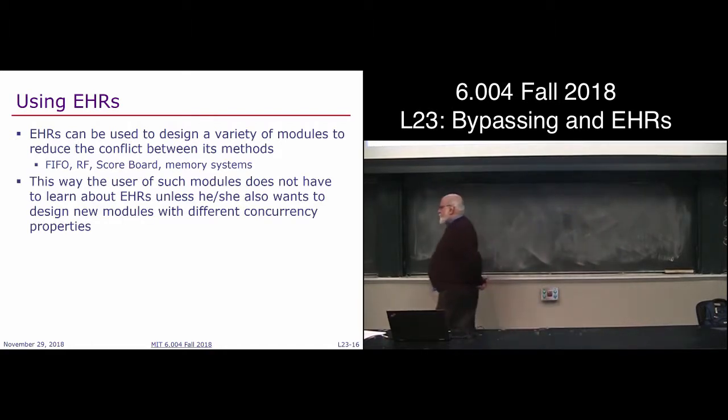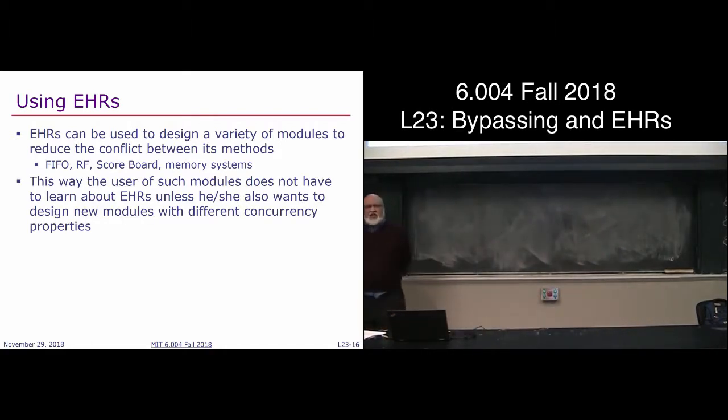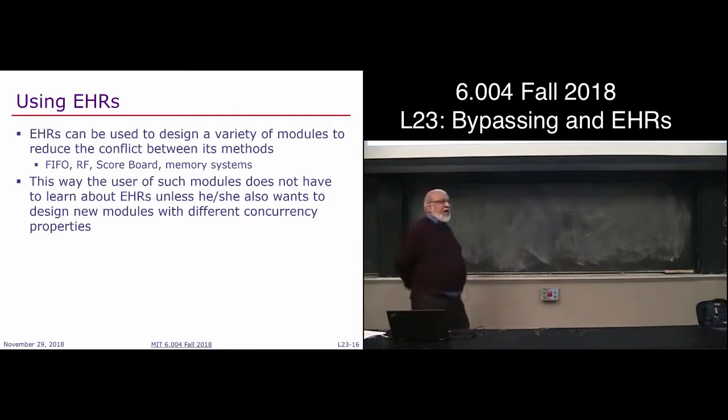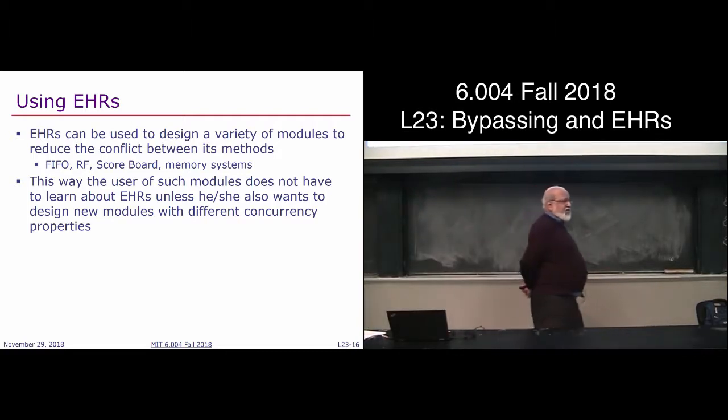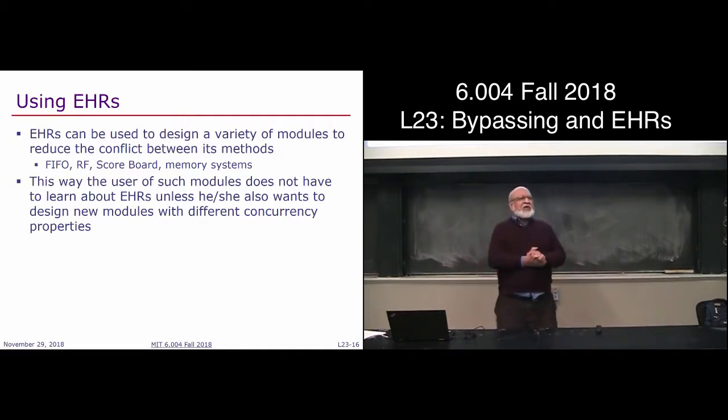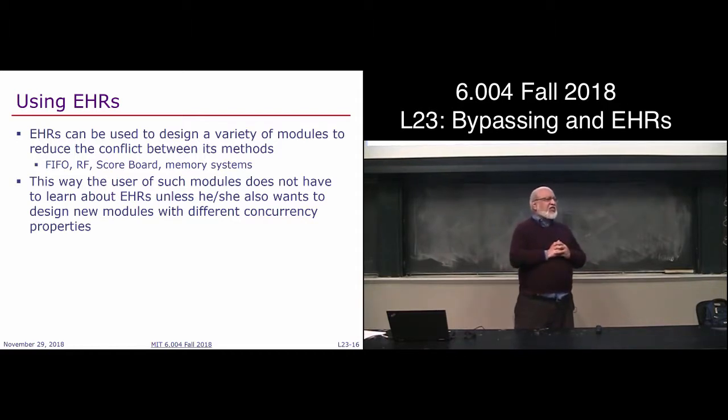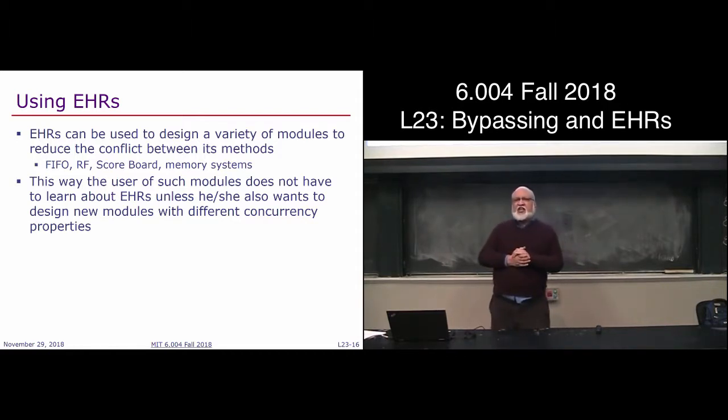Now, the good thing about such uses of EHRs is that the outsider doesn't have to know anything. In an introductory class, well, you guys are very advanced, but if you didn't understand EHRs and somebody says, don't worry about it, here is a module, use it. Here is a bypass FIFO, use it. Here is a bypass register file, use it. In the rest of your design, you don't have to worry about EHRs.